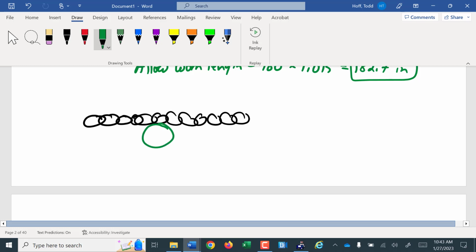It doesn't have to stretch fibers on one side and compress on the other. So we don't have that loss of strength. But the problem is the part that is bending around that pulley, now as the chain moves, those links are sliding past each other. So the portion of the chain that would be bending around the pulley is going to wear out way faster than the parts that are staying straight that don't ever have to go around the pulley.